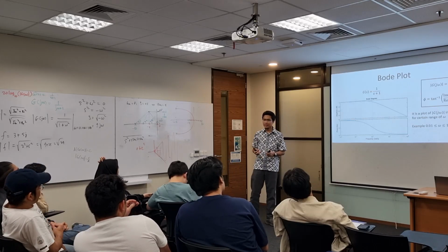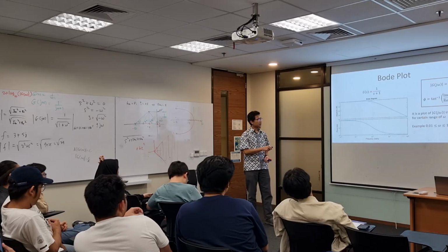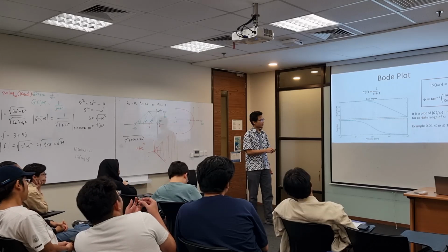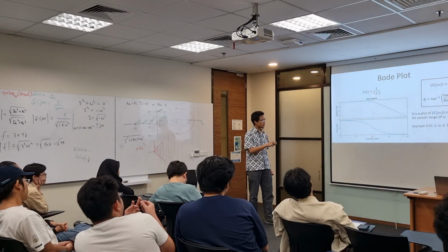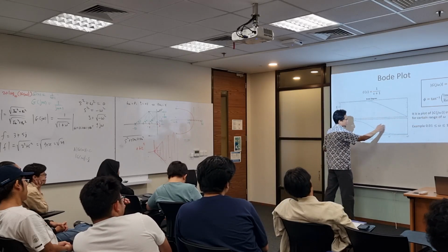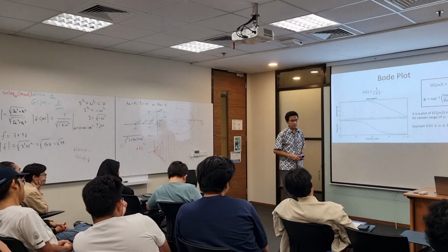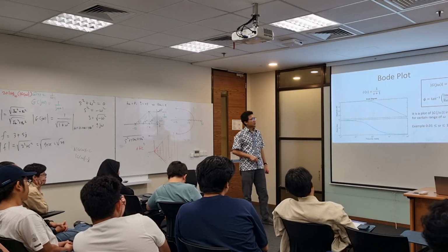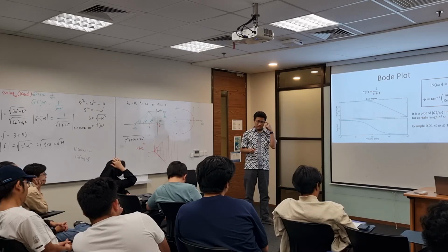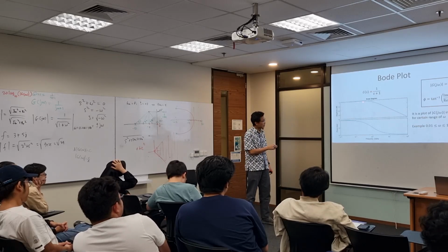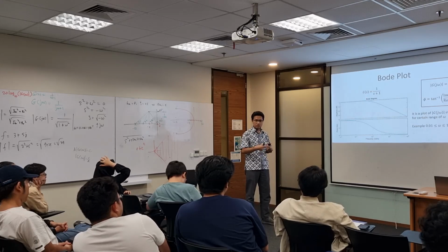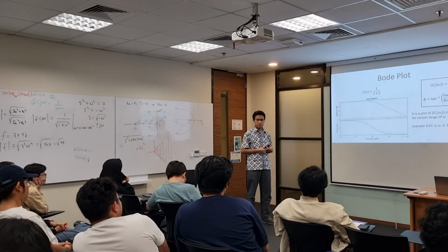So when you are introducing the compensator, you can change the pole location. You can change the value of this bandwidth. Okay, you can shift this more to the right side. So if you are designing a system, your system should work in the range of this frequency, for a very good response.